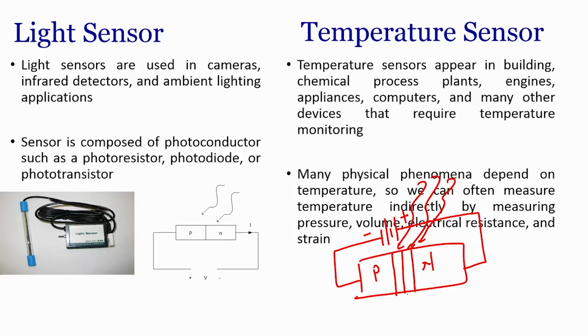So, when I have the depletion layer increased, and if I externally incident a light, what will happen? The electrons will be donated and this depletion layer will start decreasing, right. Let us understand again. If I have a p-n kind of semiconductor, and I apply a negative to p and positive to n, then there will be a depletion layer. When there is a depletion layer, if I incident an external light onto this depletion layer. What kind of biasing is this? This is a reverse bias, right.